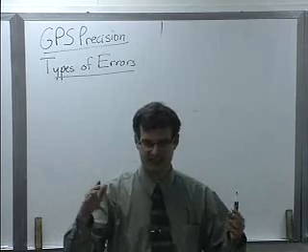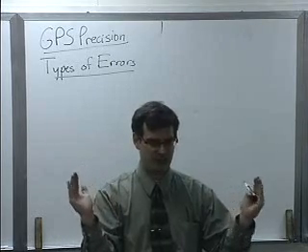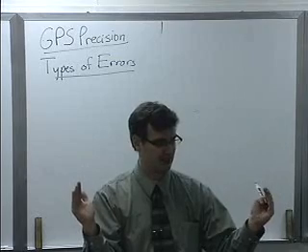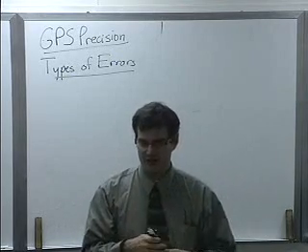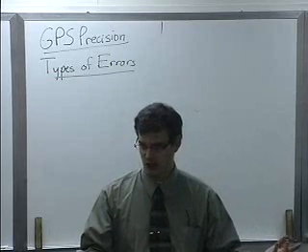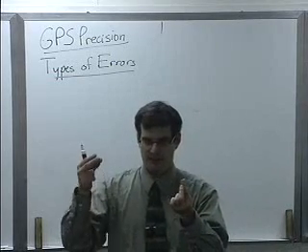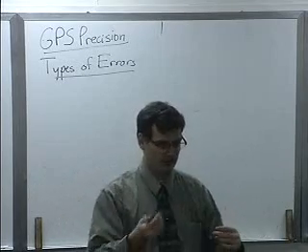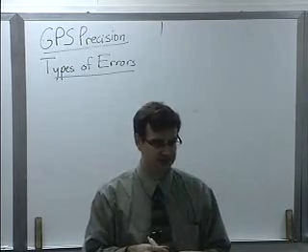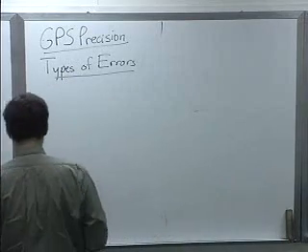So we know that's kind of like plus or minus a standard deviation captures about 2/3 of the cases if you assume a quasi-Gaussian distribution. So if we have a 3-meter error, that means that between the estimate and the ground truth, 2/3 of the time they will be less than 3 meters apart in any particular direction. So let's list all the errors.